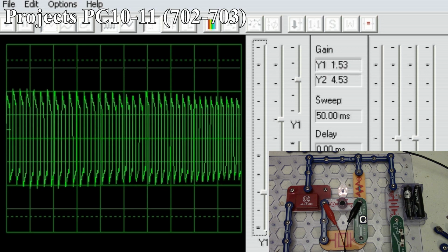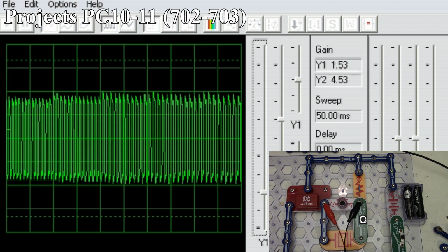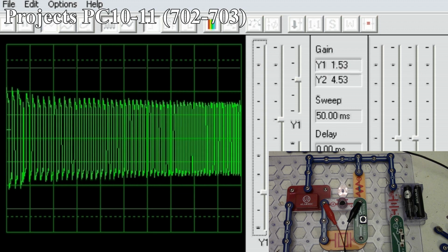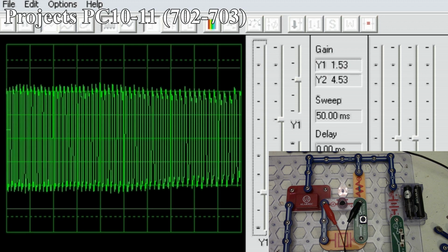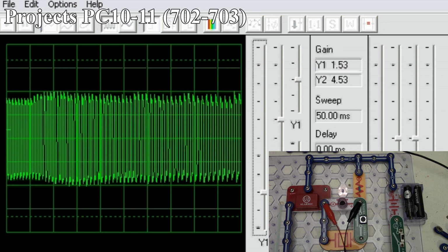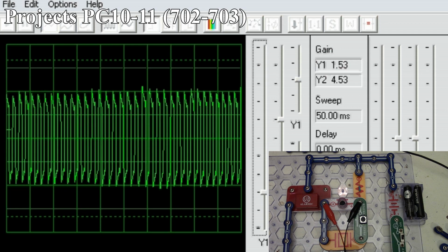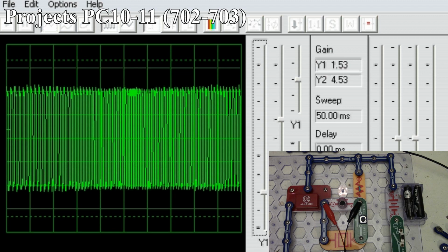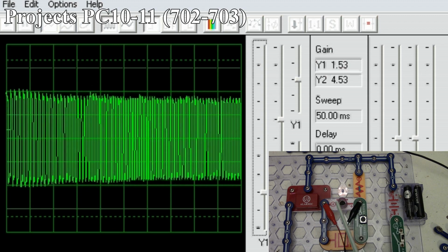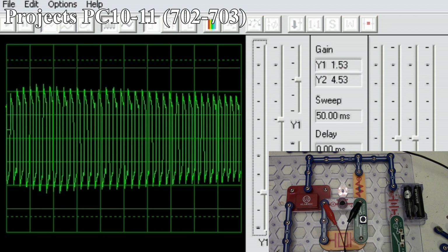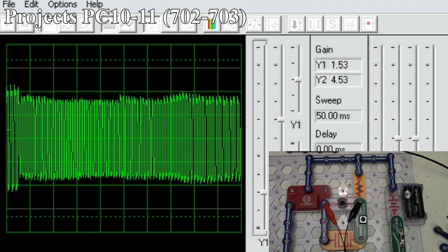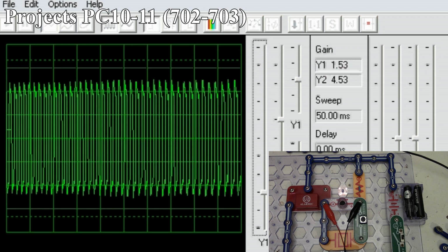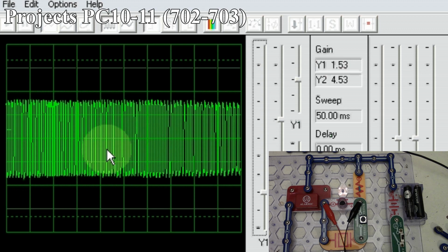And what we're doing there is demonstrating a form of modulation called amplitude modulation. So what we have is a controlling signal, which is the audio from our alarm IC coming out, which is constant there. But then we're introducing another signal by our audio going into the microphone, and that gets superimposed on top of our current waveform here.